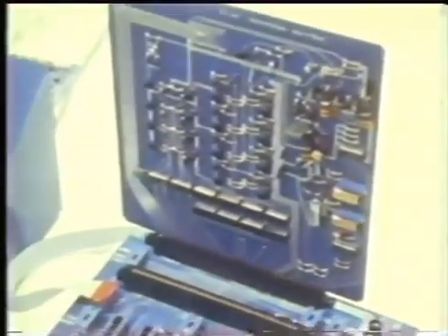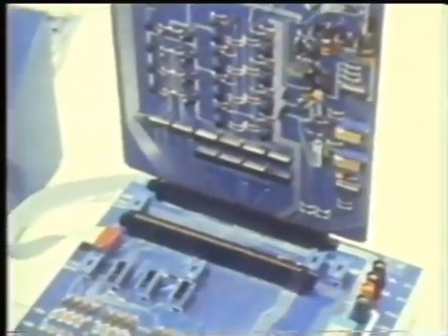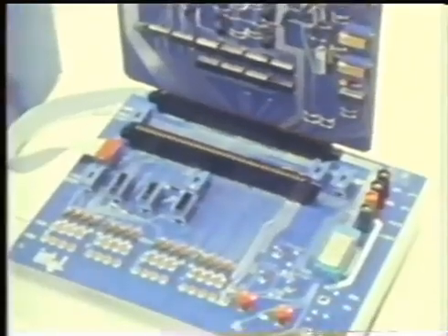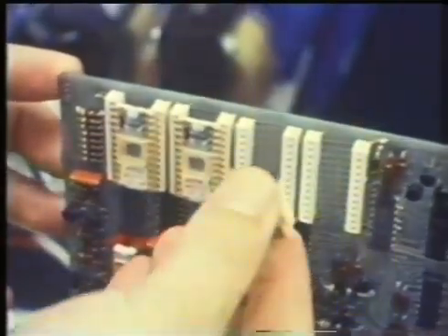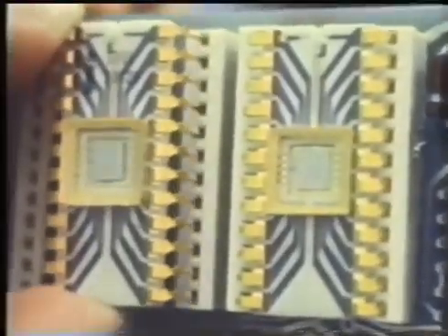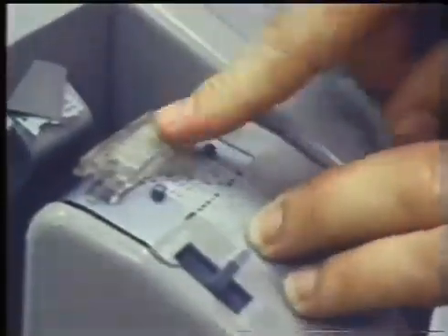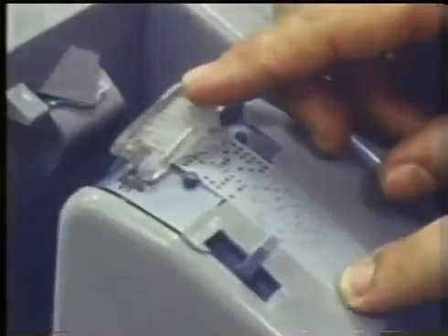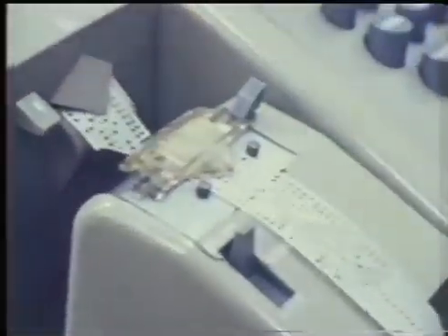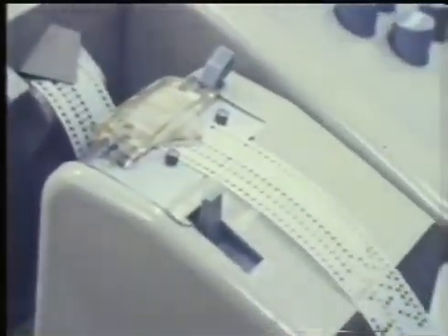The MP702 programmer card allows you to program the 1701s yourself, using the SIM board and a teletype. First, you plug 3 specially programmed ROMs containing the board's software package into the SIM board. You plug in a blank 1701. Then you execute the programming sequence, which reads your program from paper tape and loads it into the 1701 PROM.